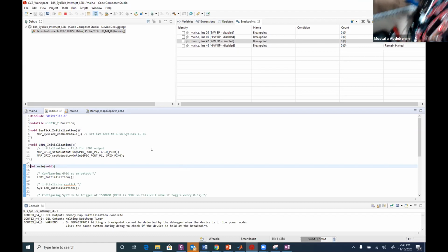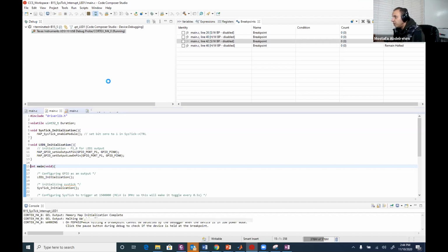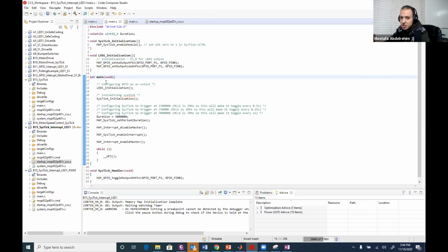And if we look at the oscilloscope, okay, it's a square wave. And again, I'm not sure if you can see, but anyways, the time is 500 milliseconds per division, and we have two divisions. So this is 1 second high, 1 second low. Okay, guys, so please code this very quickly. Then we're going to take another application for SysTick.